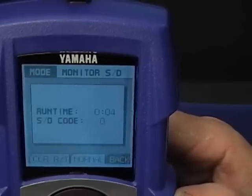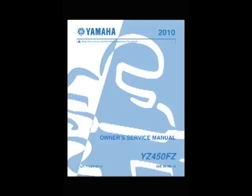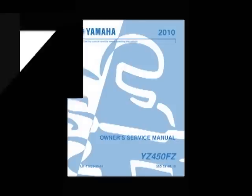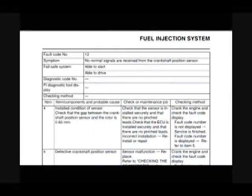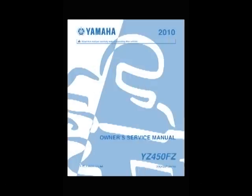In the monitor mode, you can see the fault code for a current failure in the fuel injection or ignition system. A current failure means the failure has not been repaired, or the engine hasn't been started after the repair. Refer to the Owner Service Manual for your model for more information on the self-diagnostic functions.